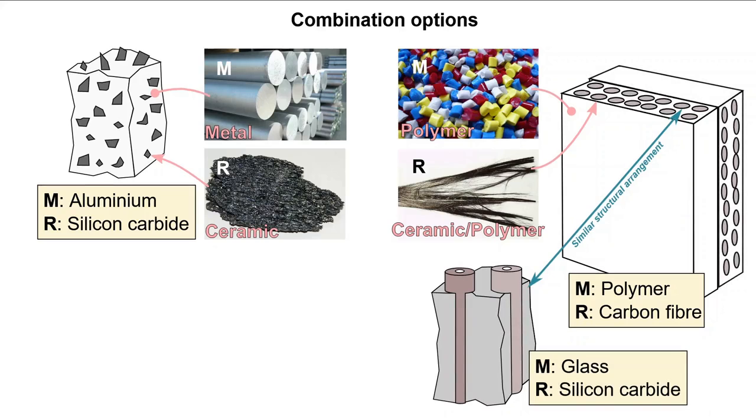Ignoring the length scale of the reinforcement can potentially deny the ability to reinforce multiple directions for a given thickness of component. For example, aligning reinforcement orientations orthogonal to each other can change the anisotropy of the overall composite. However, such a strategy would not necessarily be able to be pursued with silicon carbide monofilament for the same thickness, simply due to the size of the reinforcement.